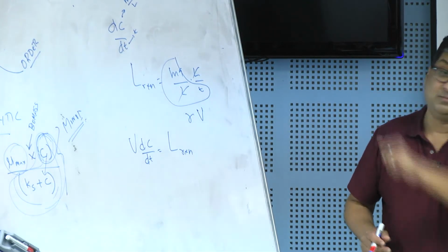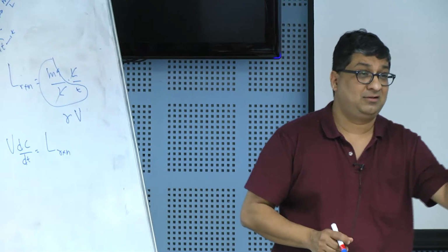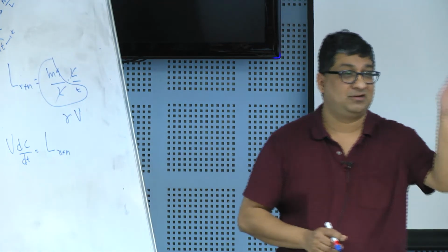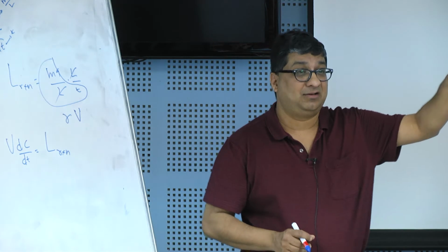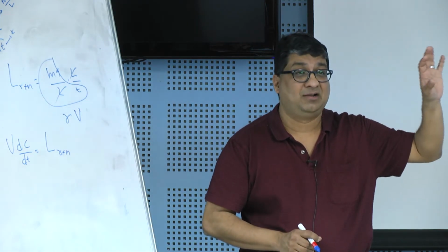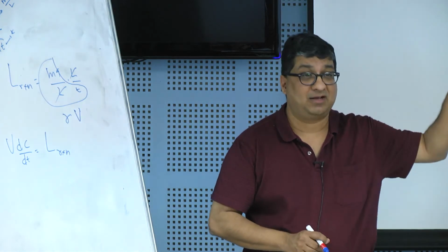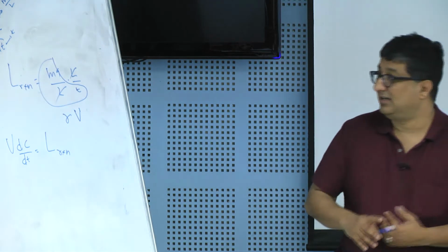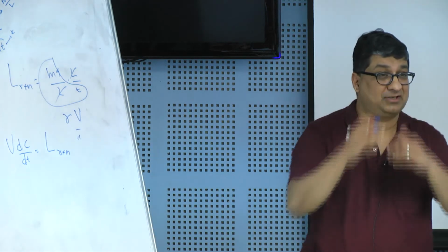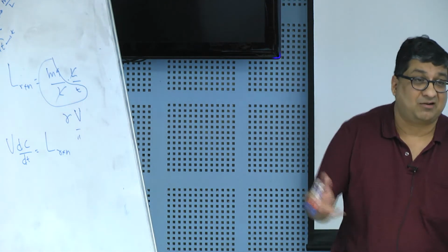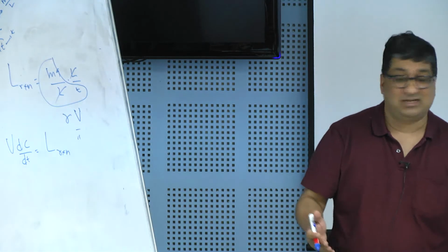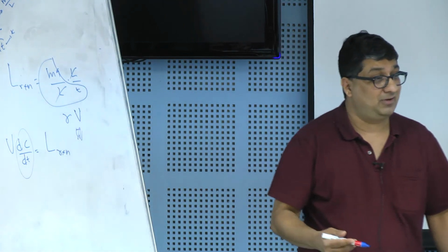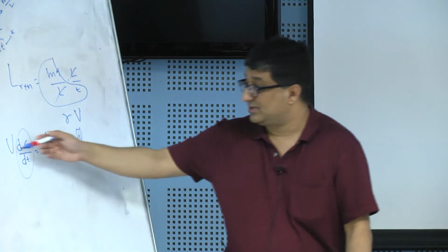So we use Darcy's law to get our advective loading, multiplying the average linear velocity, or the flow rate, with the concentration. Then we get diffusive or dispersive fluxes coming into our system using Fick's law. Now we have a loading term of what's happening in the reactor. For flux, you just divide that by the area over which the reaction is taking place, which is very hard to determine in a reactor, because the reaction is taking place everywhere. So we generally write a loading term, and that loading term is the rate of that reaction. If you have a kinetic description, it is the rate of that reaction times the volume.